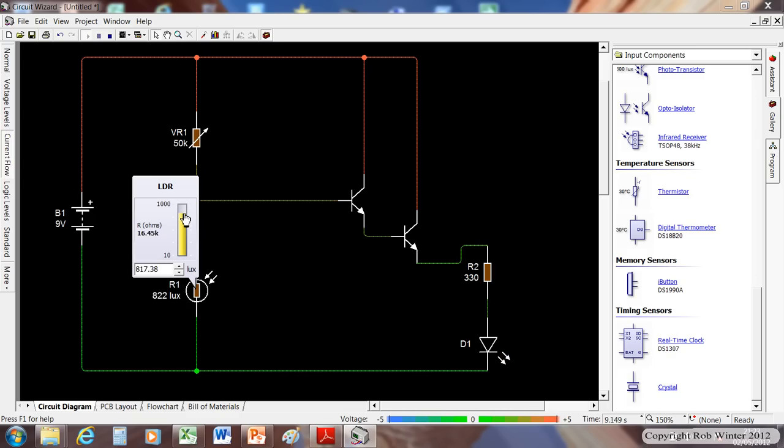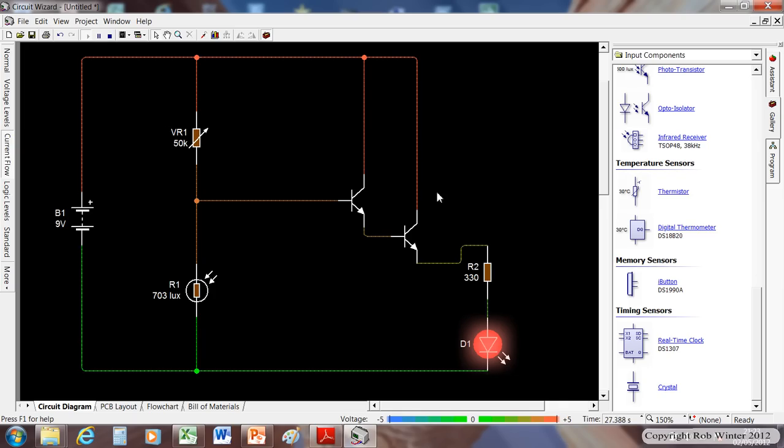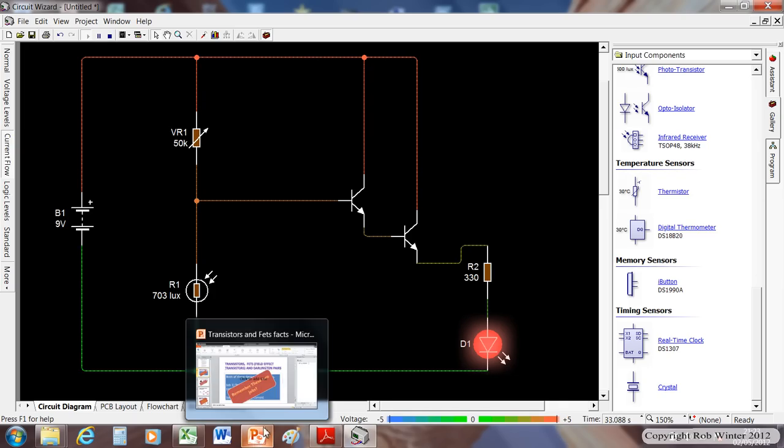This has done two things. Okay, it's made my transistor switch a lot quicker, as in rather than sort of gradually turning on and then being fully on and it taking a lot of light to affect that change, it's coming on with a relatively small difference in light. It's made my transistor not quicker but better at switching. Okay, that's one thing they do. I've set that on the PowerPoint.